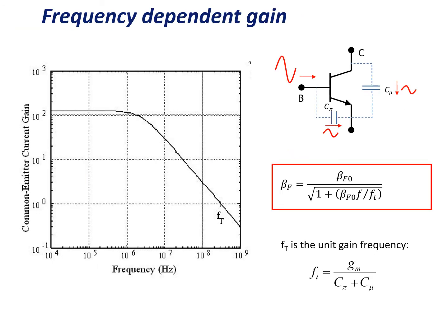Another effect that we'll see when we look at transistors in more detail is that there are frequency effects as well, and that's caused by inherent capacitances inside the transistor. The doping junctions between the diodes, in effect, between the base and the emitter, for example, produce a capacitance. And there's also a capacitance between the collector and the emitter.